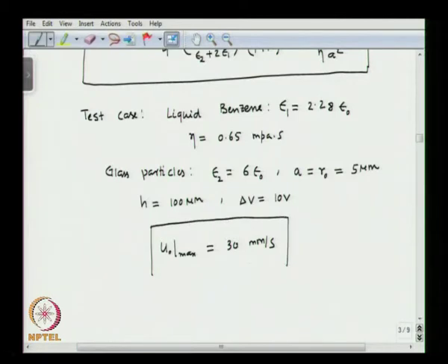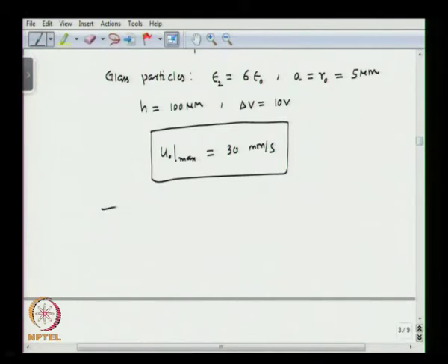So, such a velocity is actually considerably high in microchannels, which is very encouraging, because the trapping is still possible at such higher velocities in a microfluidic environment. But one necessary condition for dielectrophoretic force is that always the dielectric constant of the particle has to be higher than that of the liquid. So such higher velocity is encouraging.